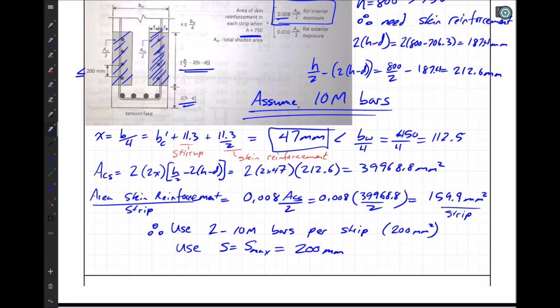Well, what we would do is specify in our details a starting point, an ending point, and a middle point for the bars that added up to some nice dimensions that would be easy for somebody to place in the field and fit within our maximum and minimums. But here, since we just have the 2 bars, it's very simple for us. We'll pick that 200. We don't want to be right at the edge because 212.6 isn't a very nice round number, so we'll pick 200.